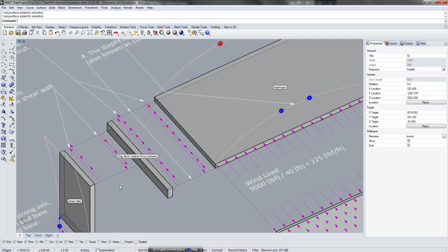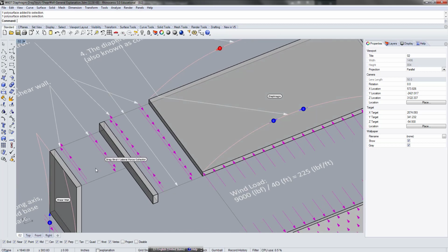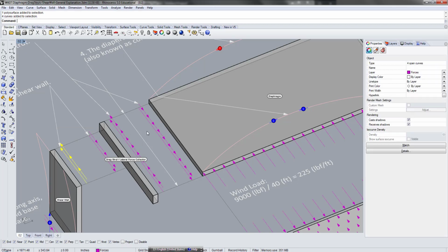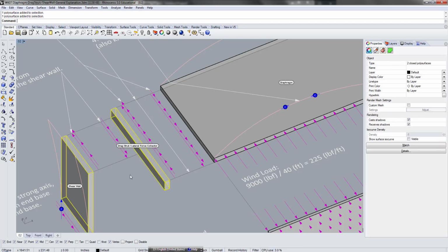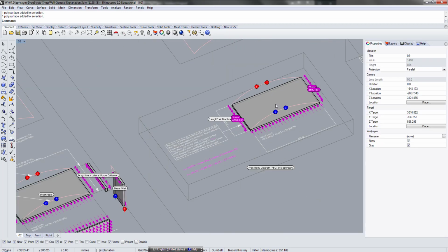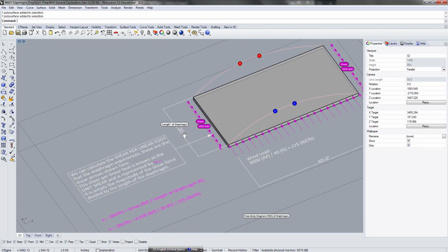So, in other words, if you try to calculate the amount of shear per unit length, it must be more intense when it's shorter than when it's longer, right? So actually, the shear between here and here, even though the total amount is the same, if you look at every linear length of these connections, there's more going on between these two. So that's basically what the shear per linear foot is about.